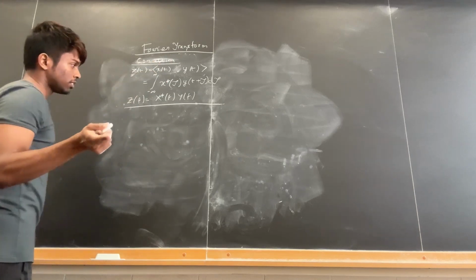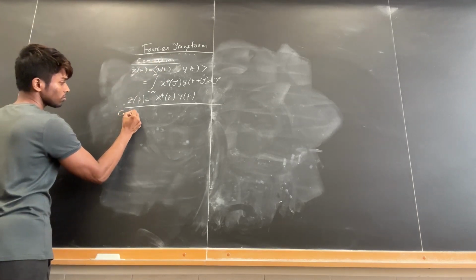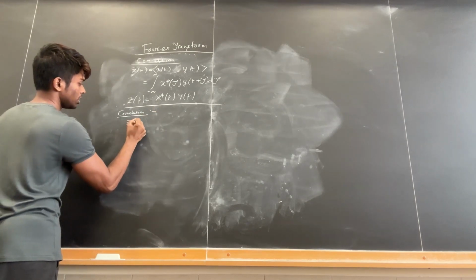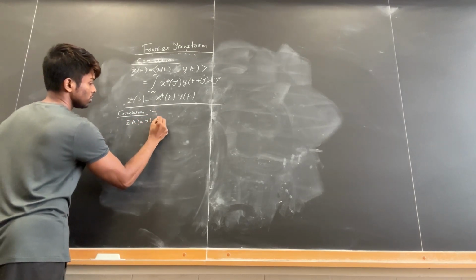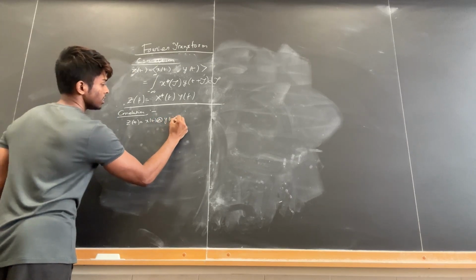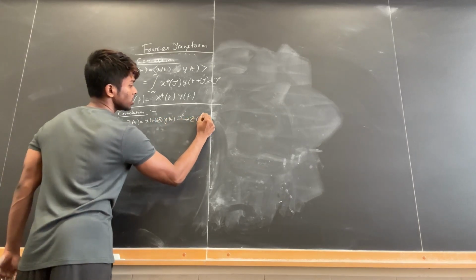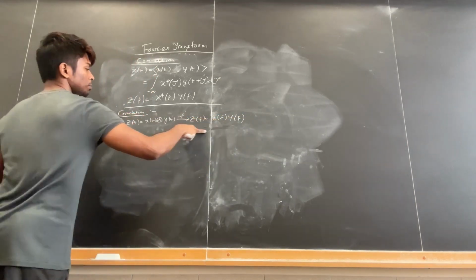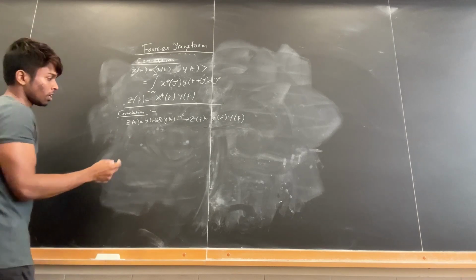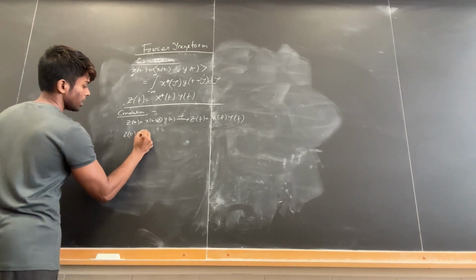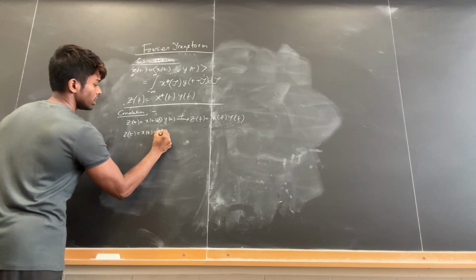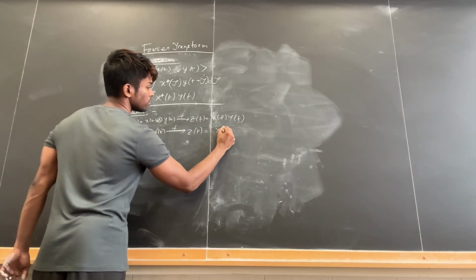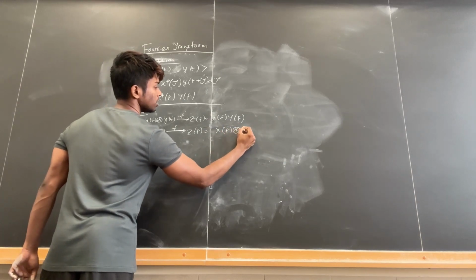But I forgot to say one thing. I want to add something to the convolution property. We did a convolution in the time domain, where z(t) equal to x(t) convolved with y(t) has a frequency domain Z(f) equal to X(f) and Y(f) multiplied. If we just multiply the signals in the time domain, what happens? So z(t) is equal to x(t) times y(t). Then in the frequency domain, Z(f) should be a convolution of X(f) and Y(f).